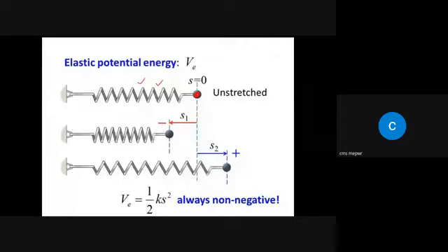As I have already told, for a spring the unstretched length is taken as a datum where we have zero deflection or zero extension. If I set right as positive and left as negative, then during compression the particle moves towards the left, so S1 will be negative. During extension it moves towards the right of the datum, so S2 should be positive. And we already know the equation for work done by a spring was half k (S2 squared minus S1 squared), right?